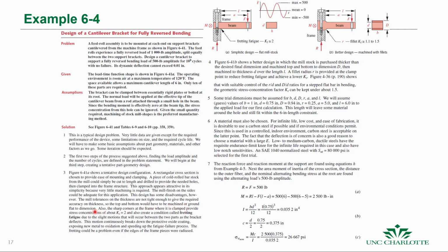Okay, and it's saying here that if we're going to put a load here, we don't know what the mill tolerance is. So if we just bought this material from the mill, it's not necessarily going to come in with high enough precision or geometry, so it'll have to be ground or turned. So this geometry here we have to consider.